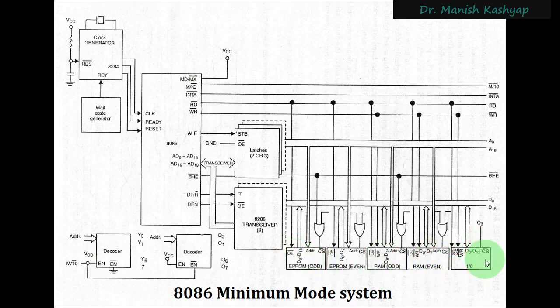There is also this input output device, and you can see that the control signals, I have shown them on the upper side. So this memory slash IO bar, interrupt acknowledge signal, read and write, they are also there, and they are also connected to these memory chips. So whenever through programming inside this microprocessor, these signals will be activated, appropriate operations can be initialized.